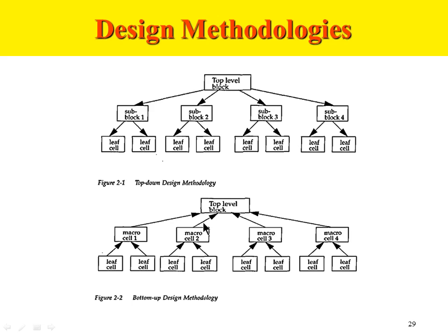This is how design is done, and verification is done by a completely different team who is not doing design. Whoever does design doesn't do verification or testing, and whoever does verification doesn't do design. The teams are different. The verification team will develop their own software model nowadays using Verilog, or some other language. You might have come across E language or Vera by Synopsys. SystemC is still used, and SystemVerilog is used. A separate model will be developed like this design.